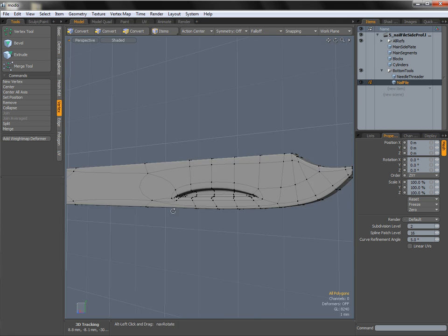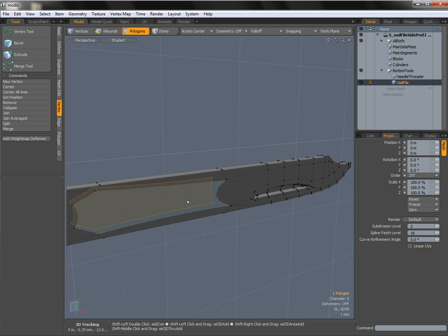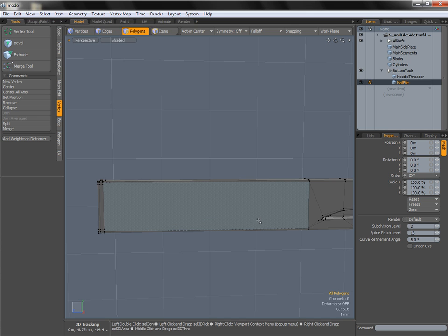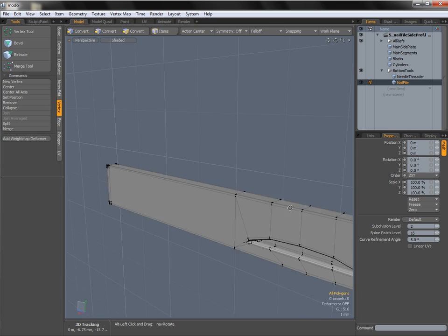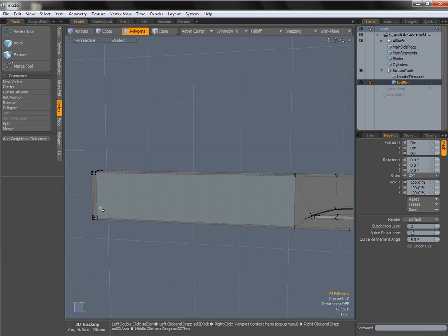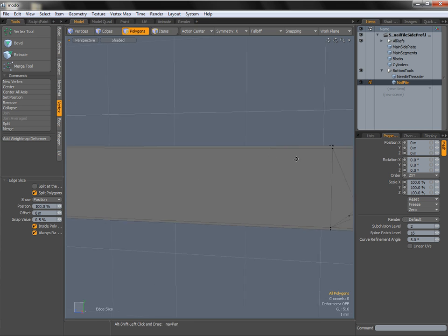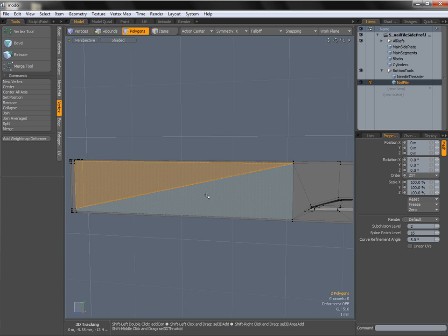So we now have one last thing that we need to do, and that is to take care of both of these n-gons that we have here. So I'm going to go to regular mode, come out of tab mode, and you'll see that both of these are the same on both sides, so we can quickly turn symmetry onto the X. And all I'm going to do is drag an edge from this top vert of this inner edge here to this very top corner over here, and that gives us these two quads.